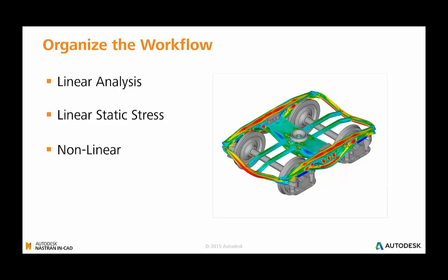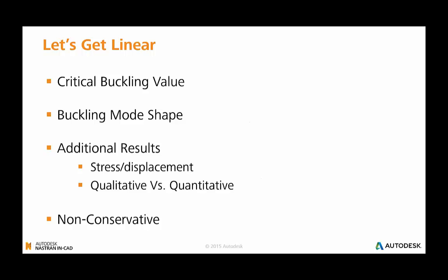The buckling load can then be used in a linear static stress analysis to understand some of the stresses in our design. From this, the linear static stress analysis can determine whether a nonlinear buckling analysis is absolutely required. And then we advise doing a nonlinear analysis as it can improve the accuracy of your buckling load prediction.